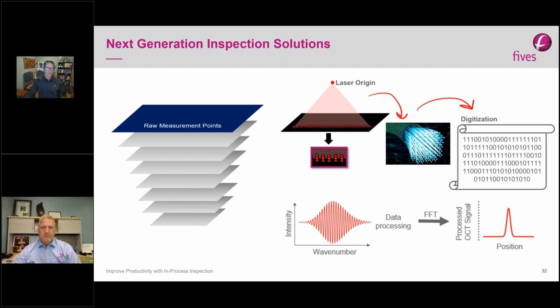The schematic of the laser scanner is at the top, and the grouping of red dots shows one scan. Each dot is represented by one measurement wave packet, which is decoded into a peak position using a fast Fourier transform. Then hundreds of these dots, or A scans as we call them, are taken in order to really accurately measure the location of one position.